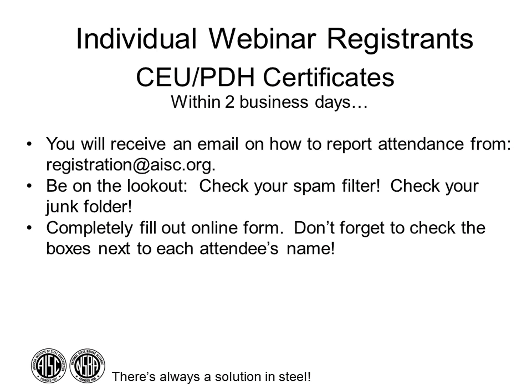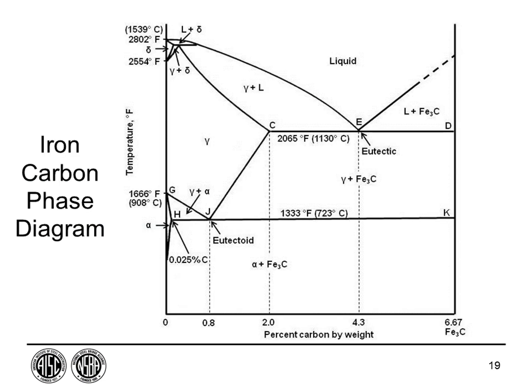I'm going to take us to slide 19. This is about slides 19 and 20. How are the phases measured during steel manufacturing? They're not. You're measuring temperature and using the phase diagram to tell you where you are. In order to develop these, you want to make a phase diagram. You have to cool it to this temperature and then stop everything, so you have to quench it and find out what you've got at that point. So it's very difficult to generate the phase diagram.